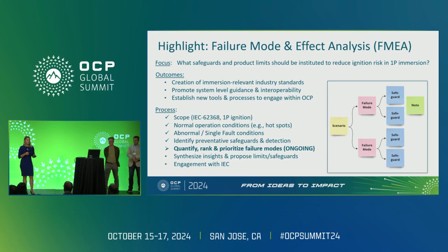The first focus of the FMEA group was actually on ignition. We saw that as the biggest concern in this space for catastrophic failure, so we wanted to start at that item. Ignition is really important. We wanted to focus on two different scenarios, focused on two key chemical properties. The first one is a flashpoint scenario. So the fluid forms a vapor. That vapor comes into contact with an ignition source, either a flame or a spark would be most typical.